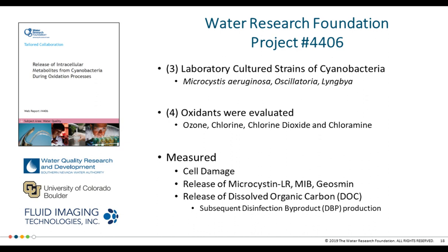Next, we looked at 4 different oxidants: ozone, chlorine, chlorine dioxide, and chloramine. And we measured cell damage. We measured the release of those metabolites that I mentioned, as well as the release of dissolved organic carbon.